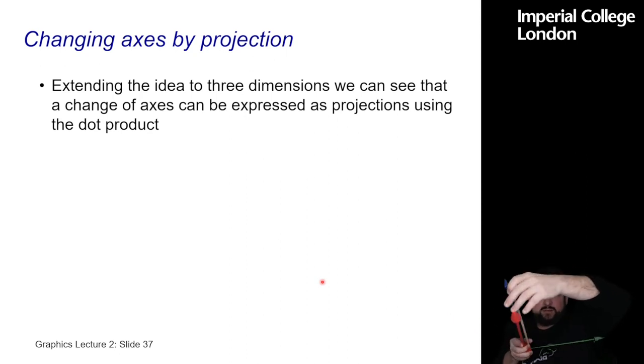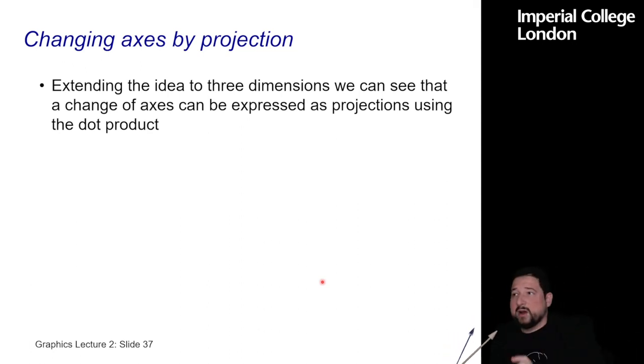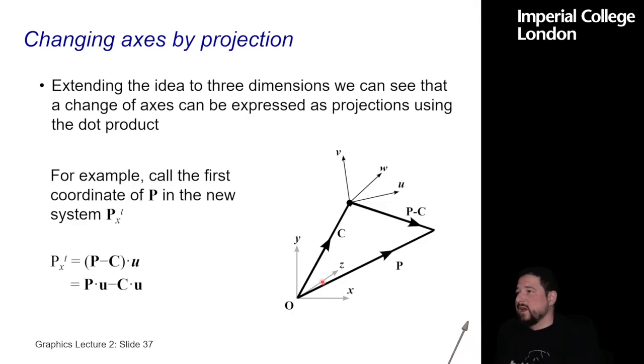I'd first project it, for example, onto X and then project it onto Z to make them parallel, to work out the axes I need to establish a new transformation matrix. So I can do this in one step, also with a transformed origin. So the only thing I need now is a new vector p minus c.